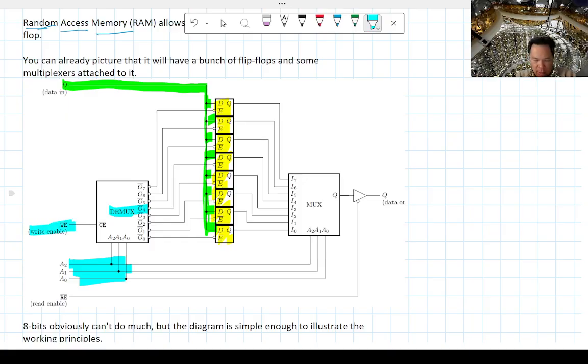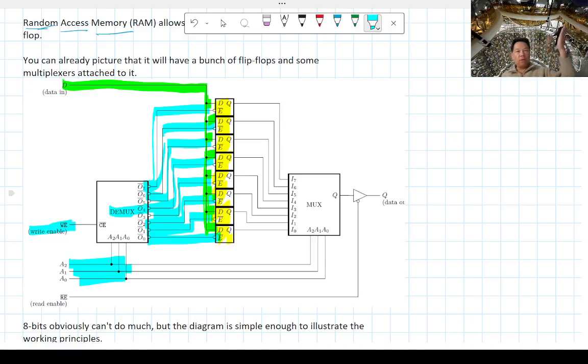And then this write enable key, not write enable key, because of the bar there, allows you to set the output to be not enabled, right? Meaning when it's 0 it is enabled, when it's 1 it is not enabled. And the selector picks which memory you're actually writing to, okay? Because if it's not enabled, then that memory just ignores the data input, and the information will not be stored or changed.